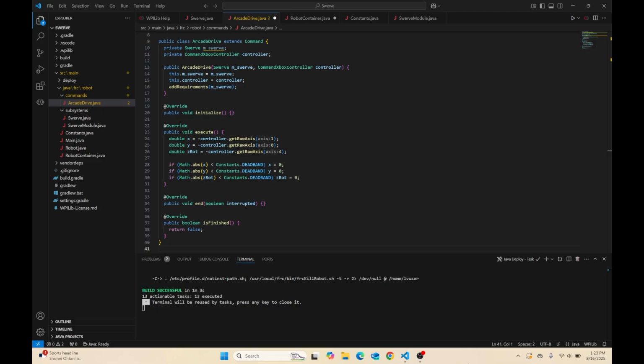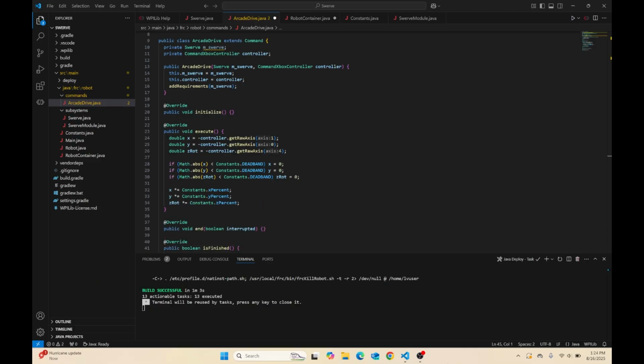You will have to tune this based on your joystick. For joysticks that are very precise, you can have a low deadband level, which allows you to do small movements easily. For imprecise joysticks, you will need a higher deadband to eliminate drifting. Now we will multiply our joystick inputs by what max percent you want to control your Swerve by. If it is your first time driving Swerve, you should set a lower percentage so you don't accidentally break anything when crashing into a wall. For reference, all of the footage shot for this video, I was running Swerve at 20% full power.